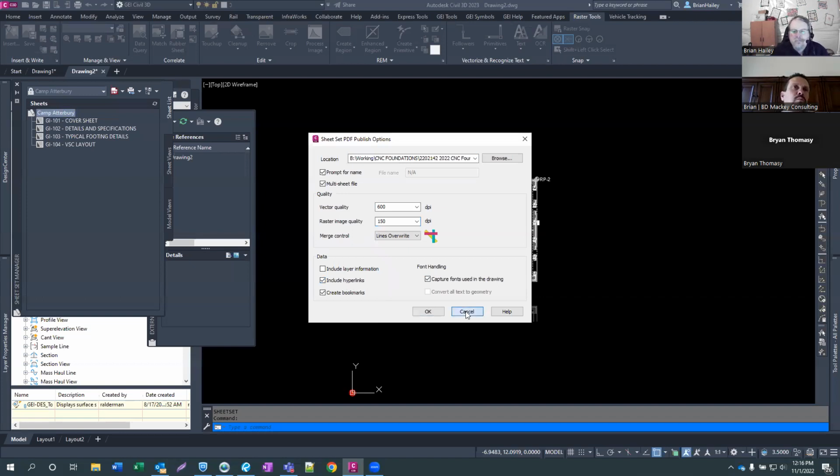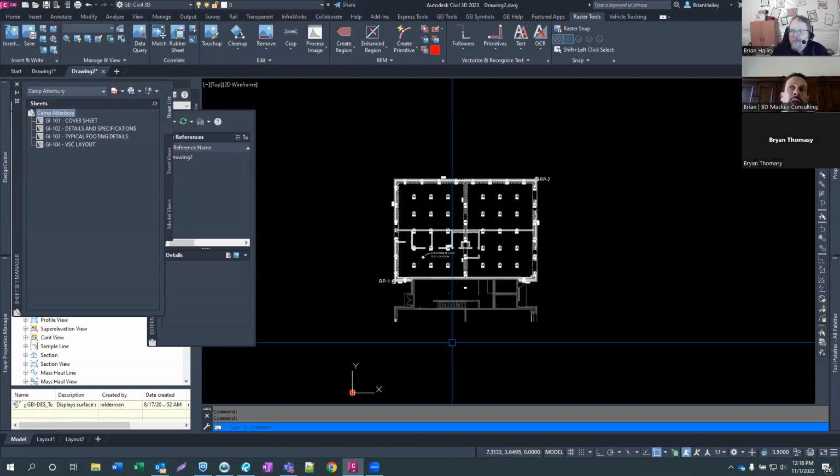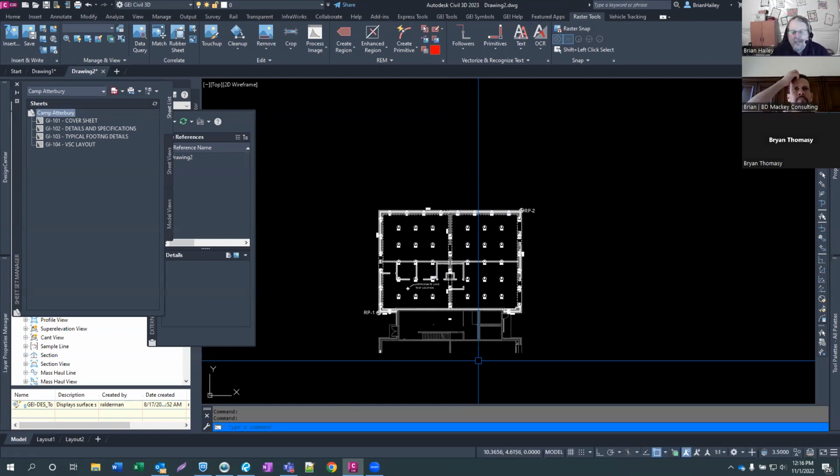Brian brought up a point on font embedding: it only works with TrueType fonts. So if you're using AutoCAD SHX fonts, that's not going to embed anyway. Correct, just with the TrueType fonts. Because an SHX font is not really a font. Yes, it's imaginary.